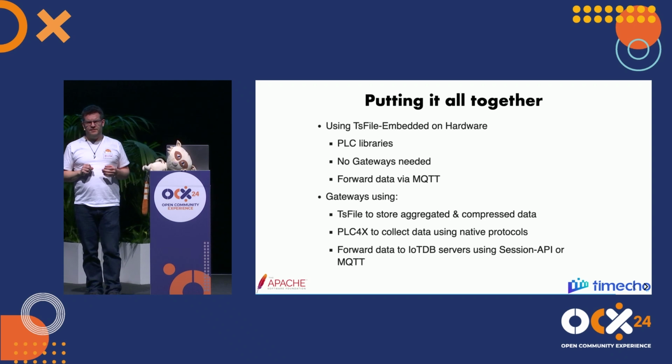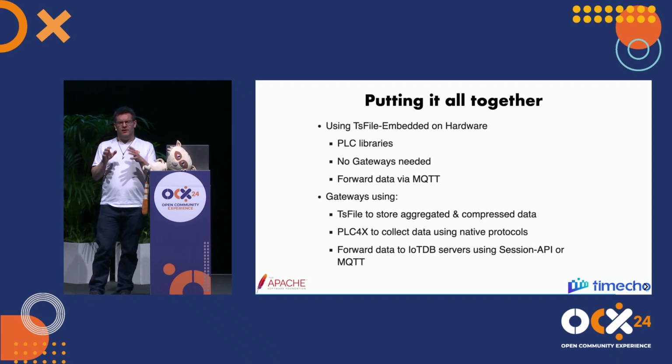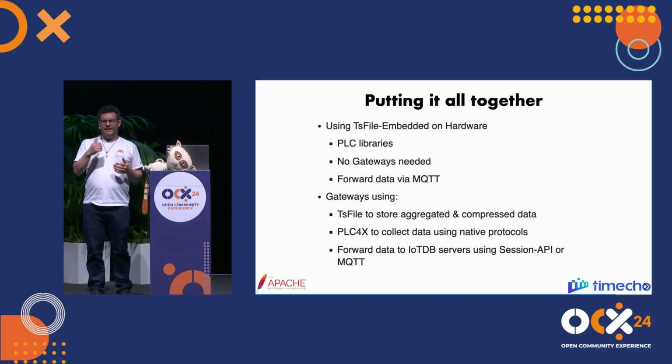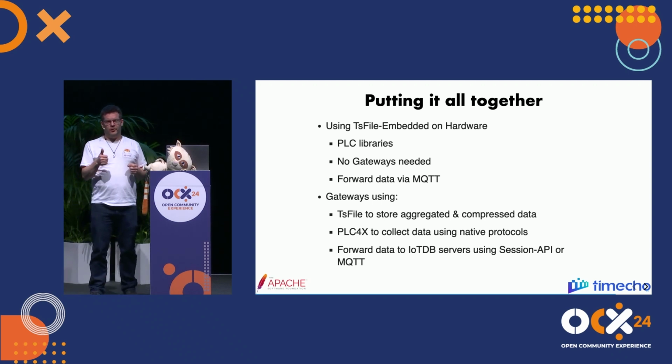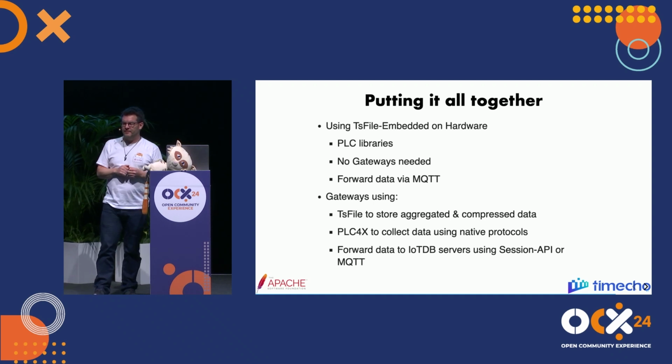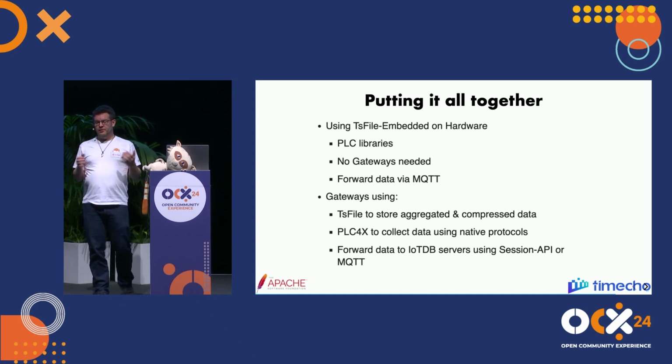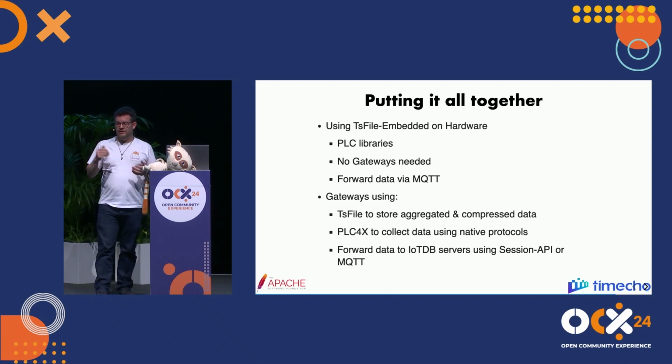I chose MQTT as a proposed protocol because all of the PLCs I've come across already have libraries for sending MQTT. And especially the network administrators know how to configure the network switches to handle MQTT traffic. Build gateways to store data locally in TsFiles.